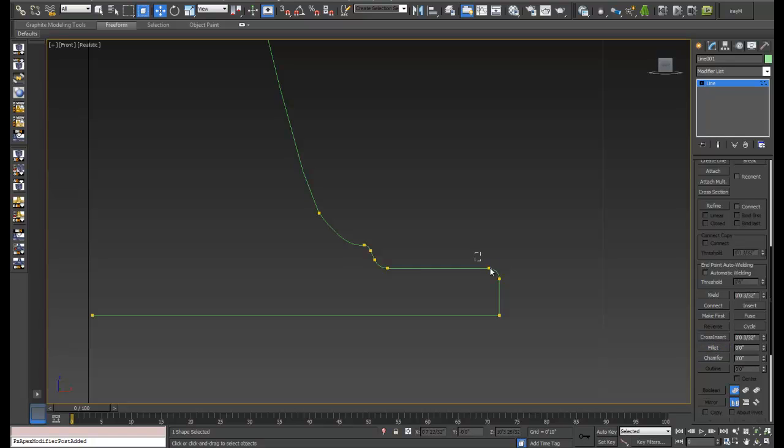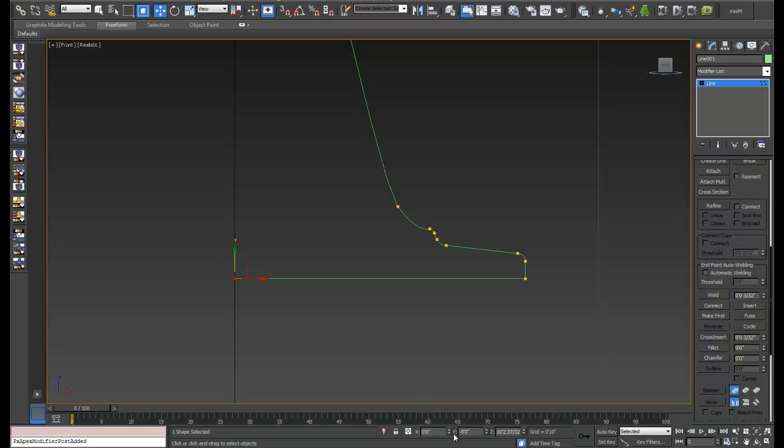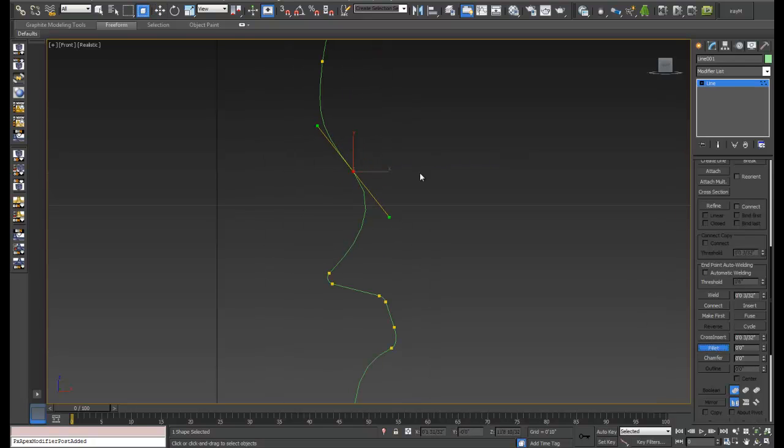Go. Pull this down a bit. And we're just looking at smoothing it out so that it's not as rough when we go to make this a 3D object. So we just want to really round off these corners, just be really refining it so that it's going to look good as we start to build the 3D geometry. So just going to add some more curves here, a little more refining, fillets, just to smooth it out. Smooth these corners off, and